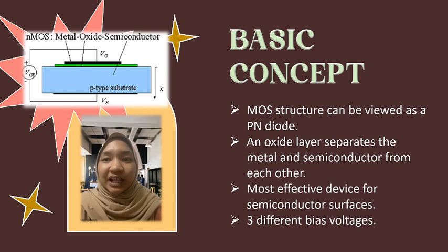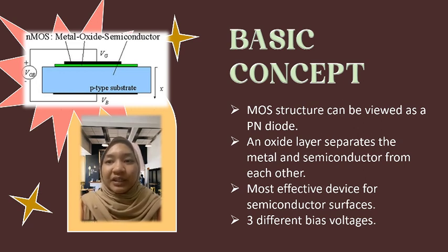For instance, at the metal/insulator interfaces, there is a continuous distribution of surface states with energies located in the bandgap of the semiconductor. The intermediate oxide layer helps prevent the diffusion of the metal into the semiconductor but also alleviates the electric field reduction. The MOS is the most effective device for semiconductor surfaces based on their practicality, reliability, as well as stability for different surface conditions.